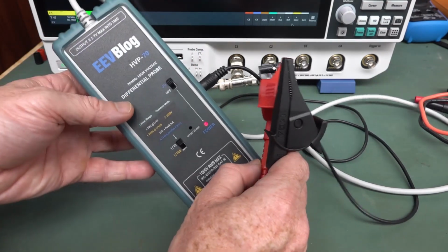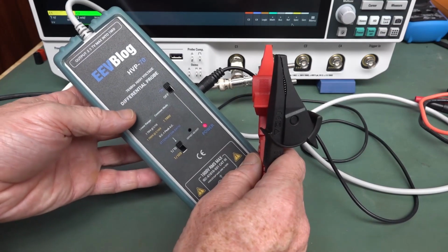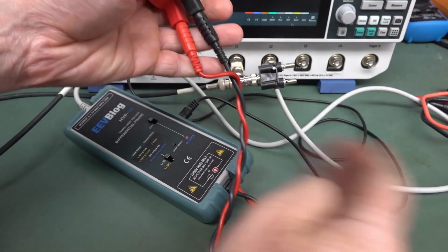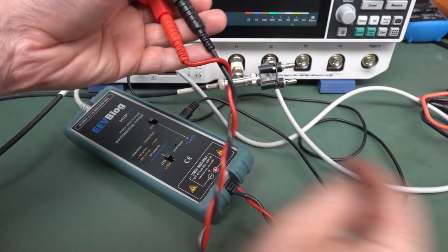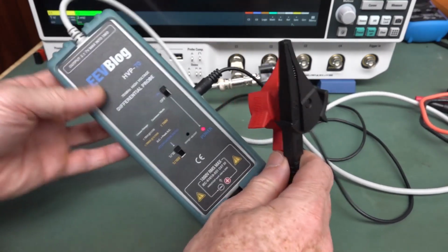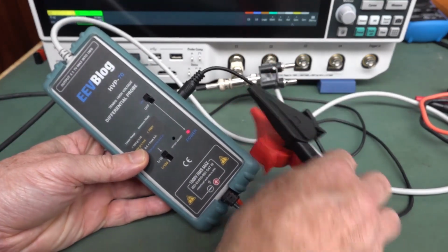So in theory, your differential amplifier should have an infinite common mode rejection ratio. It just measures difference here and rejects everything else. It has no gain at all of any common mode signal being picked up by both wires. But in practice, no, that's not going to happen.